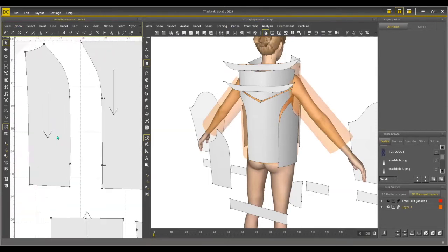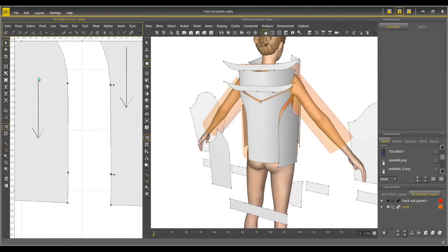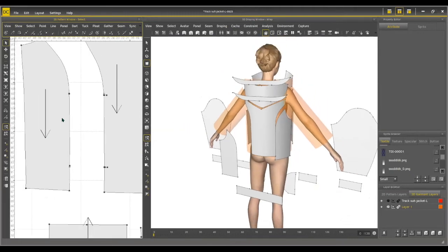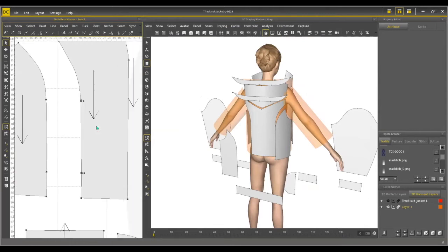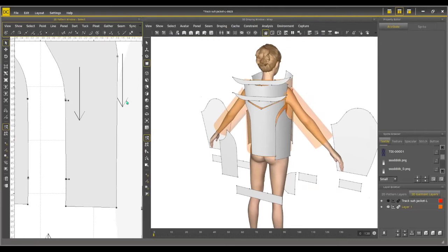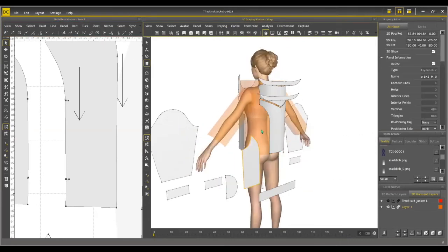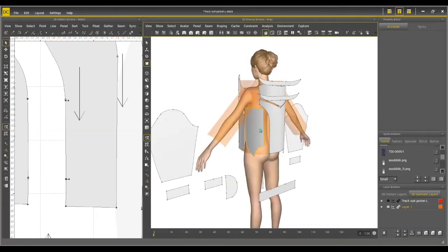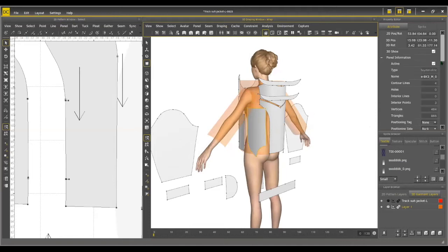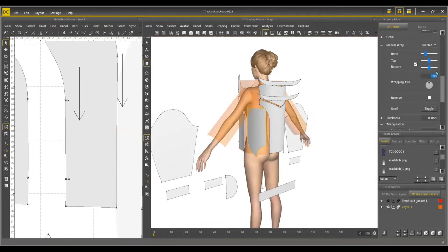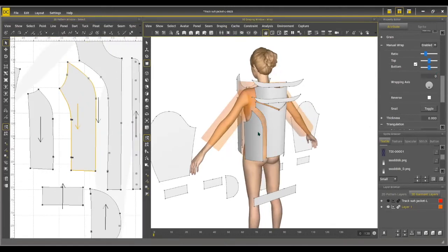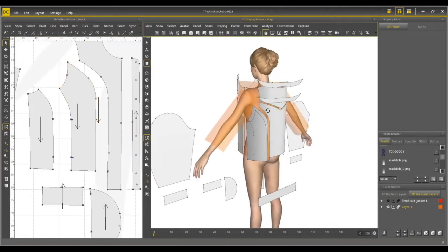There are two kinds of arrows. One is the bold line, which is about your grain direction, like how your fabric will be attached on your pattern, and the other is a dotted line arrow. It influences how your pattern wraps and attaches on the cylinder. If the direction is wrong, you can just set it to the reverse direction.